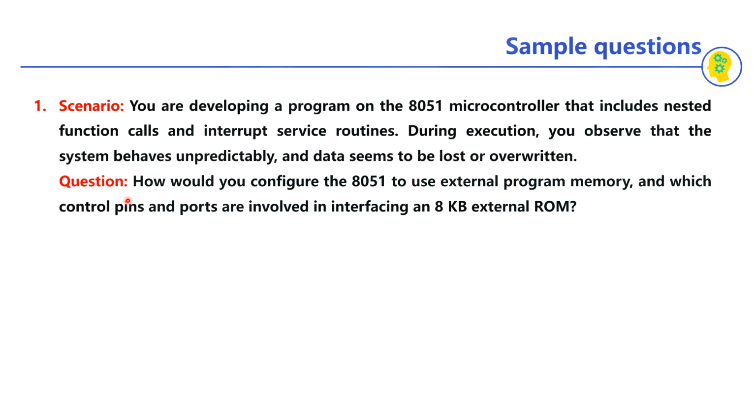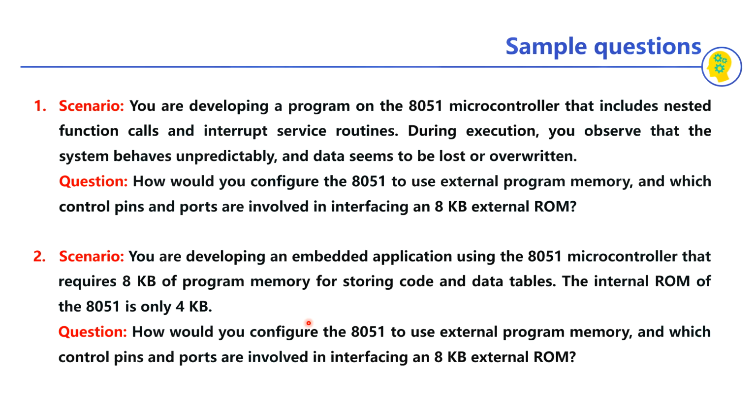Right? Question: how would you configure the 8051 to use external program memory and which control pins and ports are involved in interfacing an 8 KB external ROM? Right? So you can solve this question. That is the important thing related to this topic.